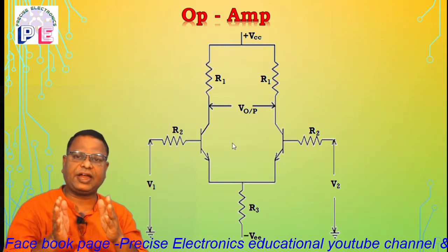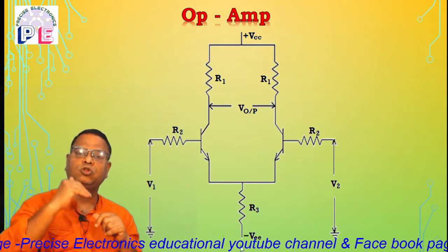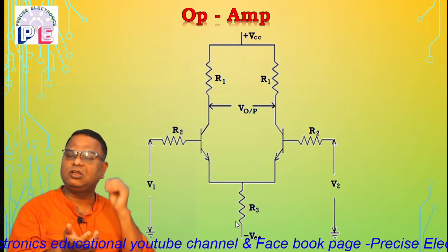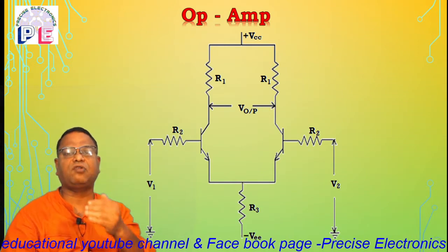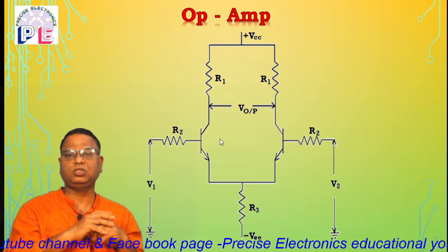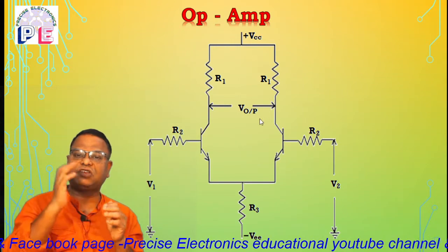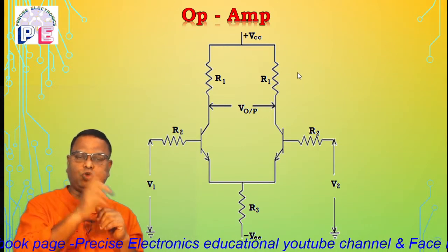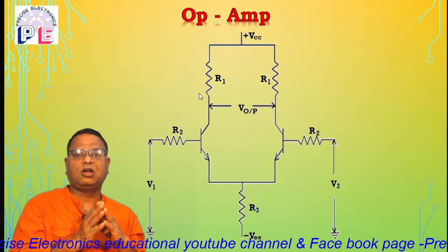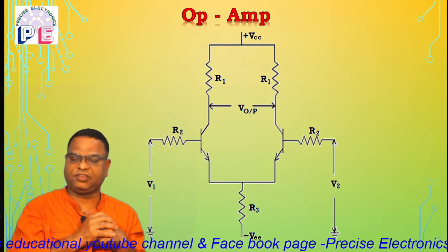The emitters of transistors T1 and T2 are short circuited and connected to the negative supply minus VEE through RE, or R3. In some cases it is considered as R3 or as RE. RE stands for the emitter resistor because it is connected to the emitters of the transistors. Then the collectors of the transistors are connected to plus VCC through resistors R1. Here again, the same resistance values are used. So R1 connects the collectors of transistors T1 and T2 to plus VCC.